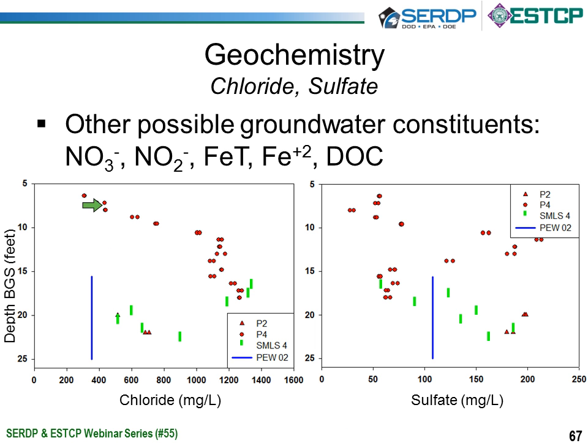In this case, you can see that the chloride concentrations increased dramatically over the 15-foot interval that we looked at, from about 200 ppm to about 1200. They then drop sharply down to about 400 and start to increase. Good correlation between well data and the passive profiler data at all locations. And to highlight one of the reasons we wanted to do this work is the results from a standard 10-foot well screen, which completely misses this very large concentration peak, the decrease and the increase, probably due to the fact that it's pulling water from a lower formation with higher hydraulic conductivity.